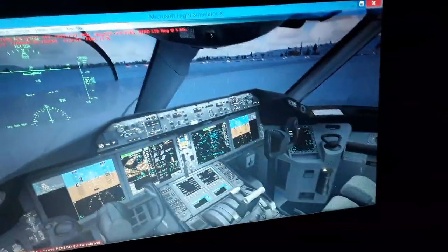We're going to make some turns and follow some waypoints. You're going to see them in the navigation display. Then we're going to initiate the descent back to the elevation of the airport, about 6 or 7,000 feet above sea level. We're going to align with the STARs, the standard terminal arrival waypoints and fixes, including horizontal and vertical navigation fixes and altitude constraints for the terminal approach and landing of the aircraft, long final and short final, and altitude and airspeed constraints.